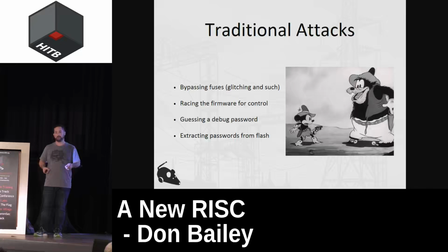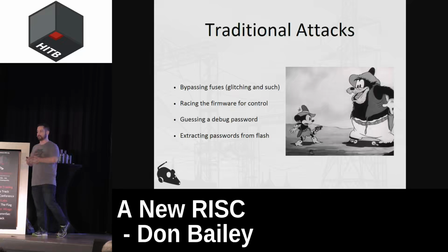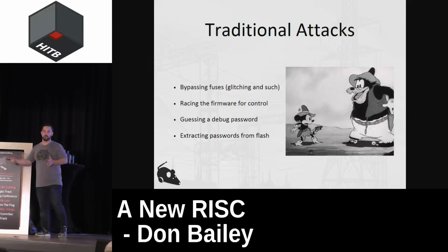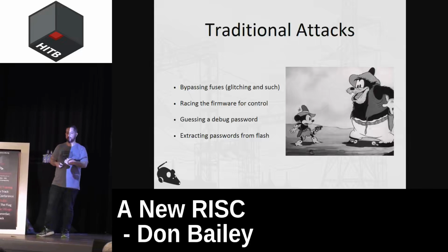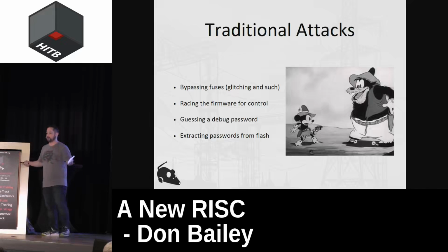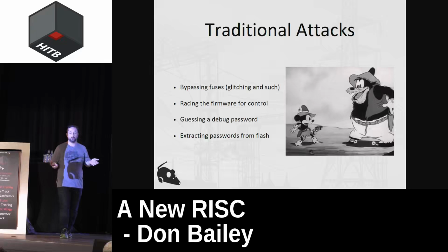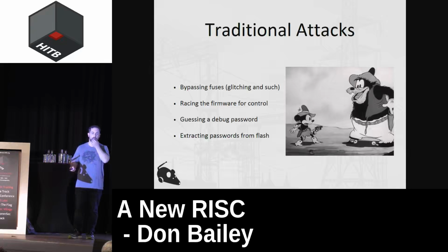Or the firmware itself inside of the system on chip disables JTAG at a certain point at boot up. So you're basically racing against that firmware to tell it, hey, I'm going to take control over JTAG or SWD or whatever it happens to be. Then you immediately gain access to the system as long as you win that window. You win that race, right?